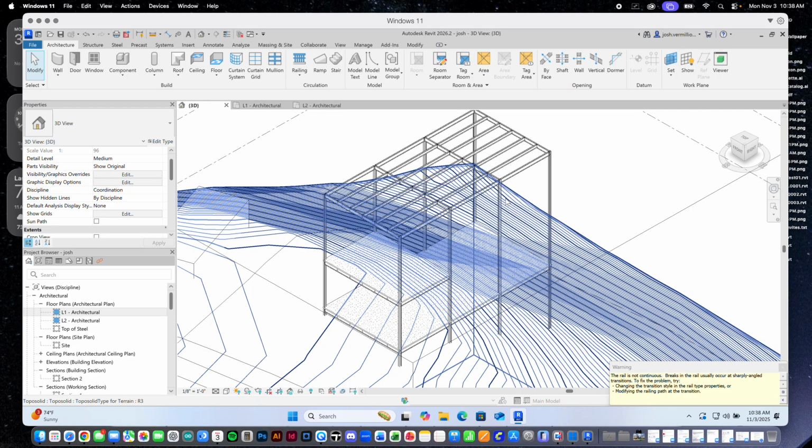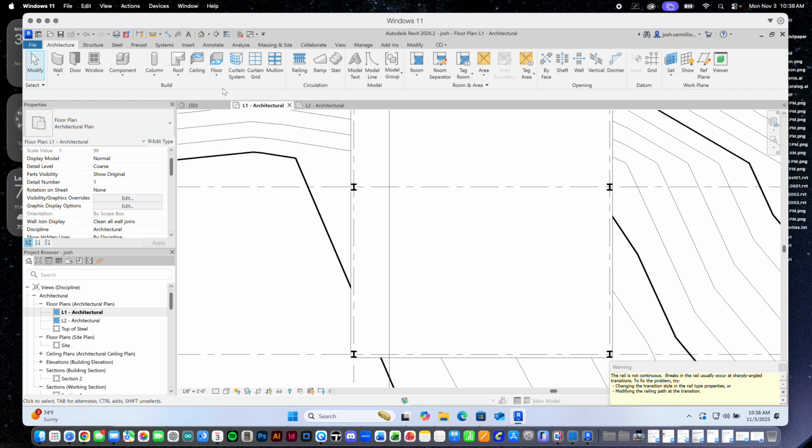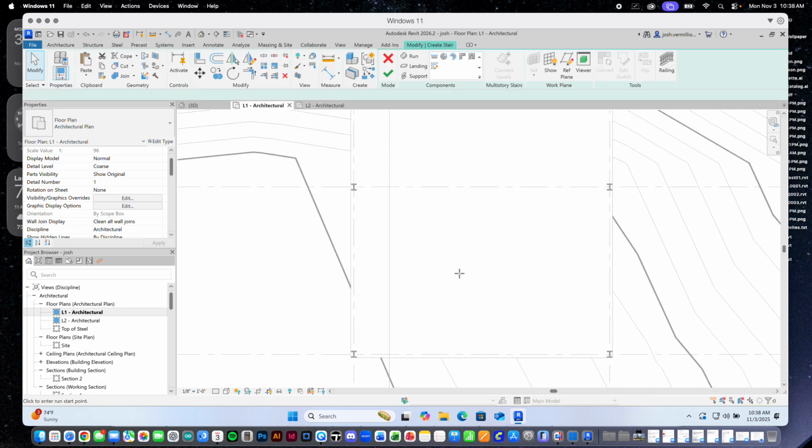Let's say you have a 6-story project you're doing. You're going to go from level 1 to level 2, and then afterwards, once you get that set, you can start to say, well, I also want the stair to go up to levels 3, 4, 5, and 6. Okay, so that's kind of how it works. That's the workflow. So I'm going to go to level 1, and I'm going to go to architecture, stair.